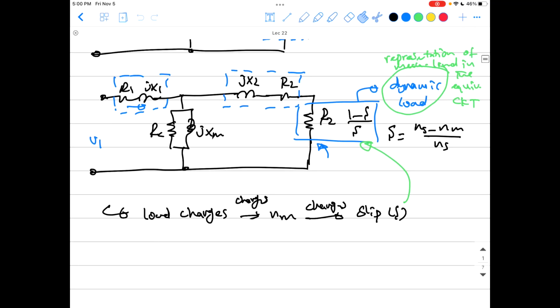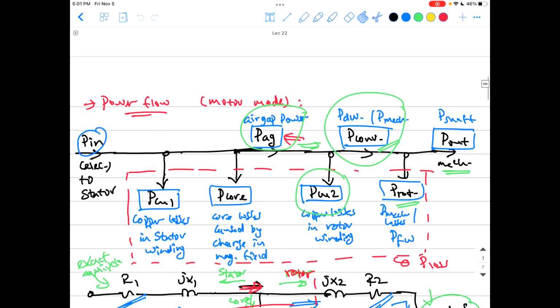But like we said before, we cannot use such an equivalent circuit to model any kind of machine unless we make it unique for this machine, and this is done by determining the equivalent circuit parameters related to a certain machine. So this equivalent circuit can represent any three-phase induction motor. What makes it describe a certain machine in your hand is that those parameters R1, X1, R2, X2, RC, XM, those 6 parameters, relate to that certain machine. How to do this? By testing it in the lab.